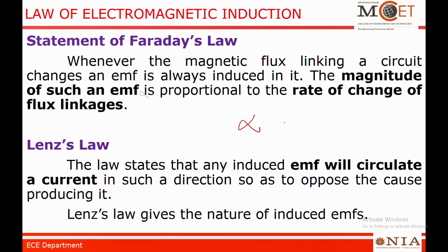And then Lenz's law says that any induced EMF will circulate a current in such a direction that it automatically opposes the cause producing it. So this Lenz's law gives us the nature of the induced EMF. The magnitude of the EMF produced is proportional to the rate of change of flux linkages, which is Faraday's law. And Lenz's law says the EMF will circulate the current.